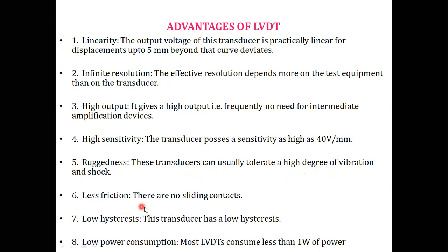Less friction. There are no sliding contacts. The friction part is very low. Why? Because there are no sliding parts here. Low hysteresis. This transducer has low hysteresis and low power consumption. Most LVDTs consume less than 1 watt of power. All LVDTs use much less than 1 watt of power. And